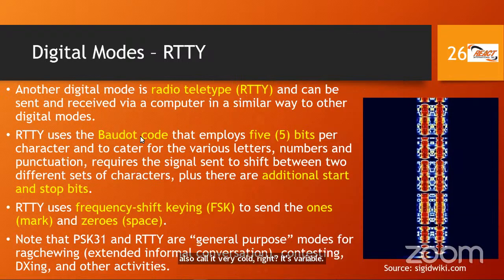But with respect to RTTY, it uses 5 bits per character. So no matter what the character is, it uses 5 bits. And we need to know that there's also a start bit and a stop bit. And those are actually exam questions that you will encounter. The other exam question in relation to RTTY is that RTTY uses FSK. Remember from our last session what we said FSK was. It means frequency shift keying, FSK.